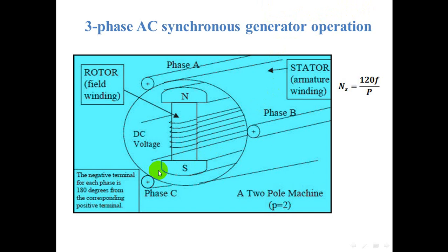By applying Fleming's right-hand rule, current is induced in conductor AB from point B into A, and current is induced in conductor CD from point D into C. So the direction of the current can be indicated as A, D, C, B, and the direction of current in the previous horizontal position of the rectangular turn was A, B, C, D.